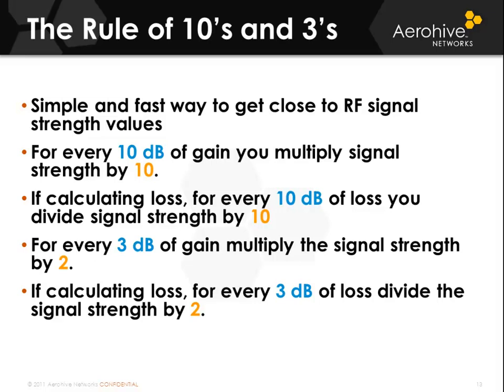Again, for every 10 dB of gain, you multiply your signal by 10. For every 10 dB of loss, you divide by 10. And for 3, if it's gain, you double. And if it's loss, you divide by 2.